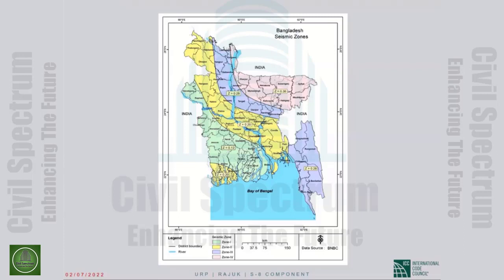Depending upon the predominant period of the earthquake, the lengthening of the period of the building may put it in the critical range or may take it out of the critical range. So what would happen, you do not know. So those who want to play it safe, they design a building that can withstand the design earthquake of the code with the infill intact.